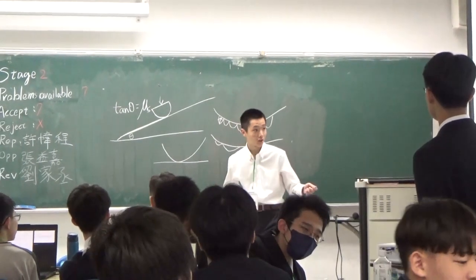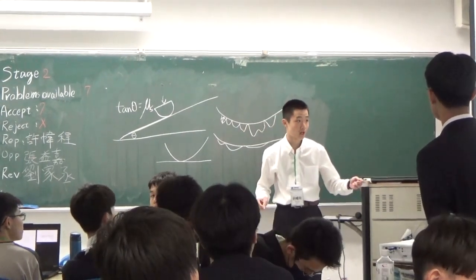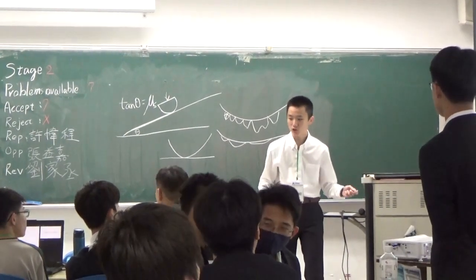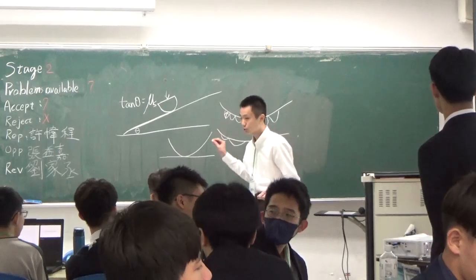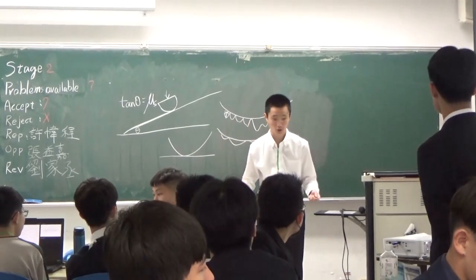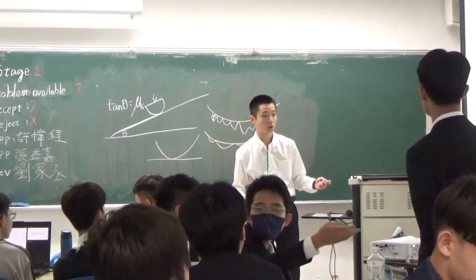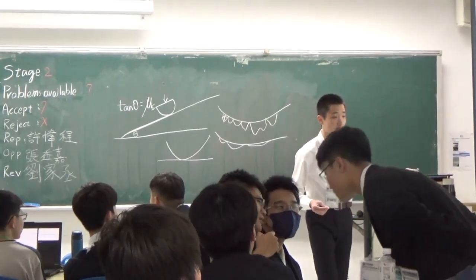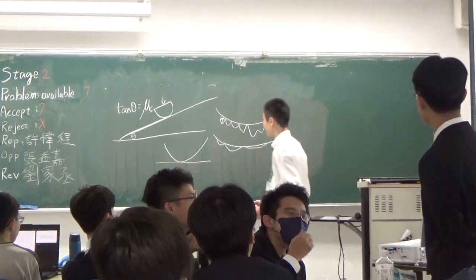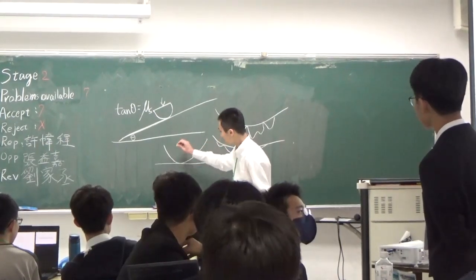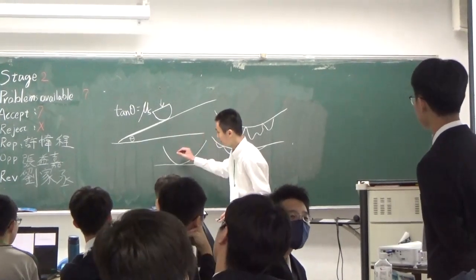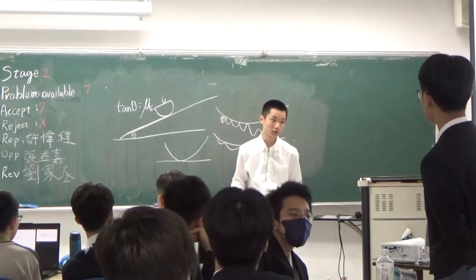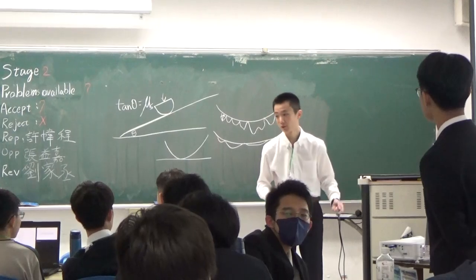And because in this part of the coefficient of friction, when the normal force is bigger, the actual contact area between the ball and the ruler will get much bigger, so the coefficient of friction will be bigger. And for the final part, the coefficient of friction starts to decrease, mostly because the materials in the plastic ball release when the pressure is too big.